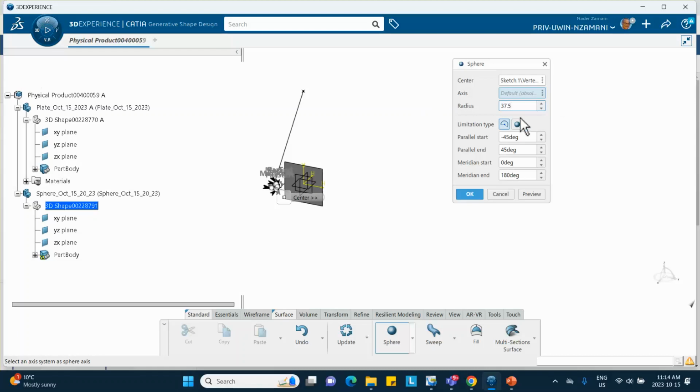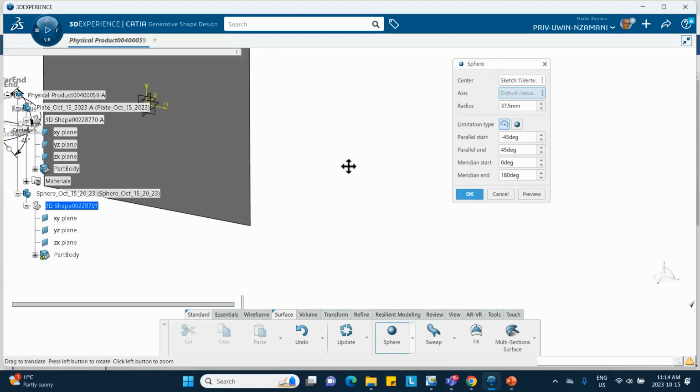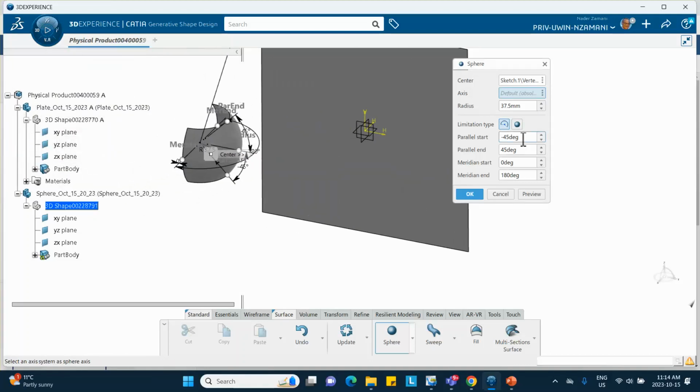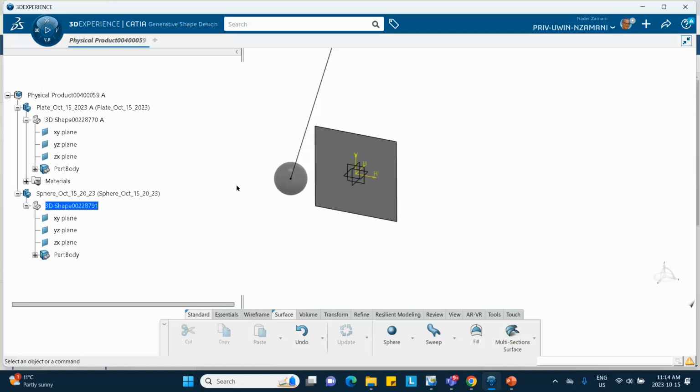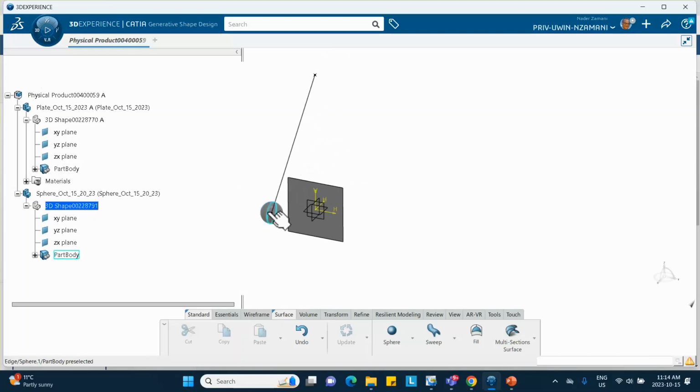Okay, now if you look carefully, you see that this is not the full sphere yet, but with these numbers you can control how it closes. So minus 90, go all the way around. Notice that it went to minus 90. 90, it goes the other way, goes this way, and then this 360 to cover the other side. Okay, it's a full sphere now. Now, in tutorial 7, because this was going to be meshed, I put a material on this, but the material values were entirely dummies. So here I don't have to do that, so I just leave it the way it is.